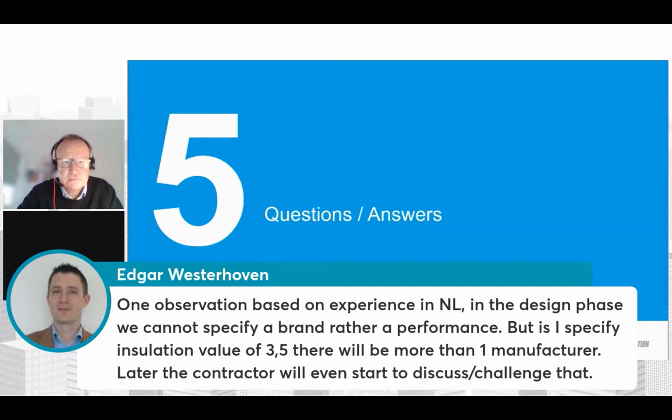Generic, and when it's possible to specify, of course we will compete somehow, so it will not replace, let's say, the classical way, but we can maybe avoid some big mistakes. For example, it must be mineral wool instead of another insulation product, without talking about brand name. In one greenfield project the mineral insulation was changed, and in fact it provoked a big fire, so we can avoid some cost problems by the end of the project or something in the future.